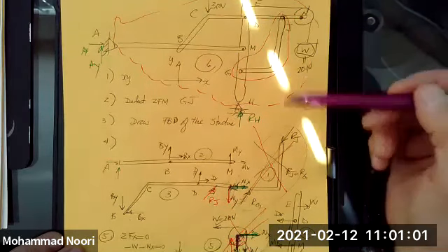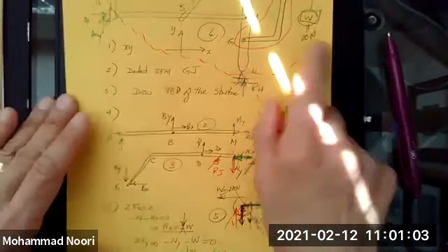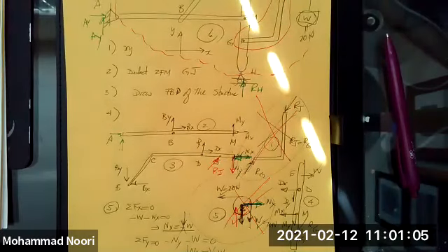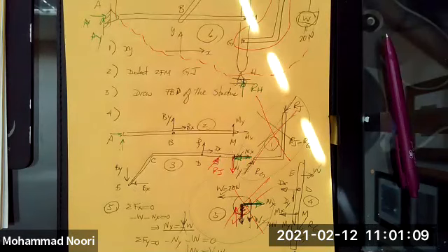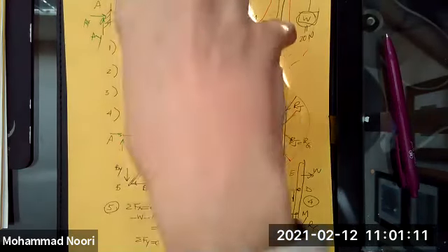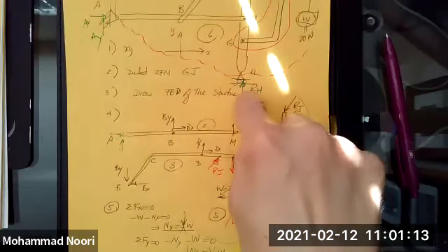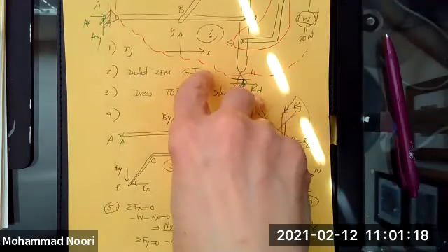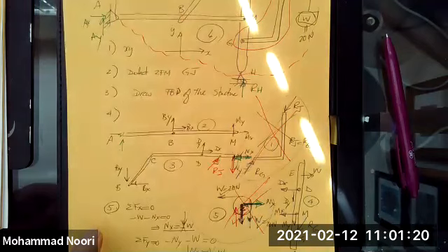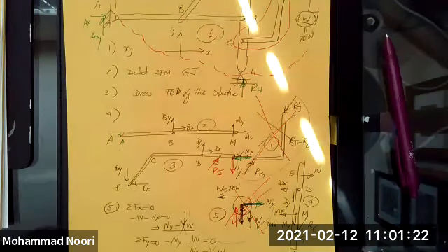The reason I didn't go with that one first, which you could, because you've already seen how to solve for external forces, is that sometimes the structure may have a free body diagram that has more than 3 unknowns. So the general procedure that I strongly recommend you follow is a methodical approach.